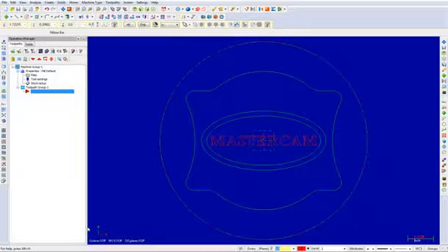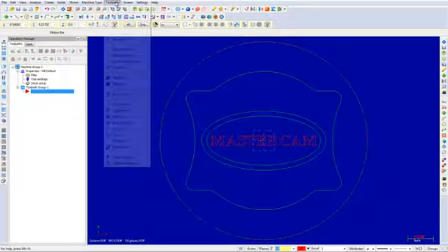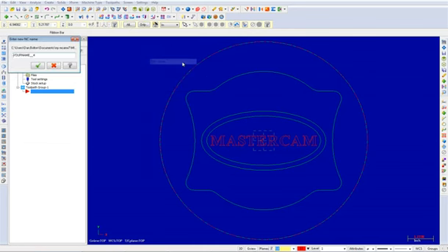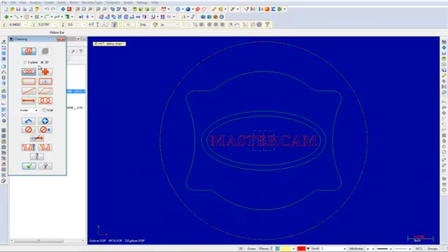As well, an inner chain defines the limit of the toolpath. Select Toolpaths, 2D High Speed, Core. If a prompt appears, enter a new NC name, and select the OK button to accept the default. Leave the default settings in the chaining dialog box.